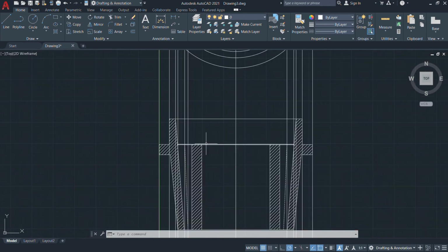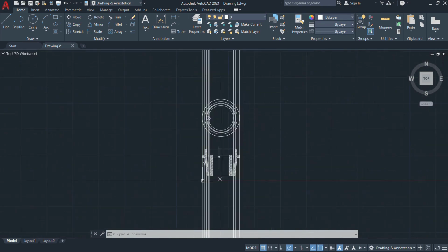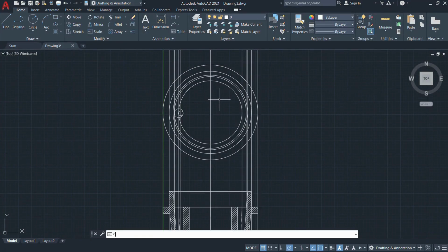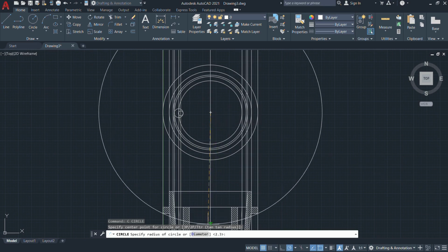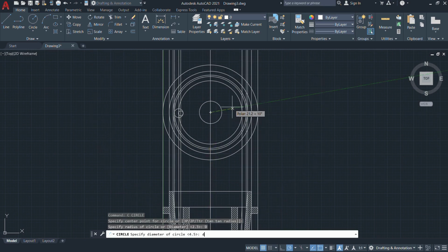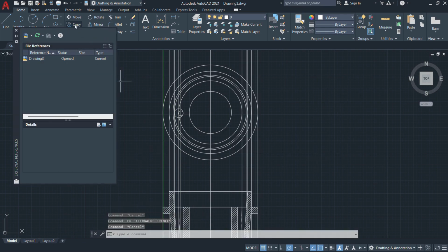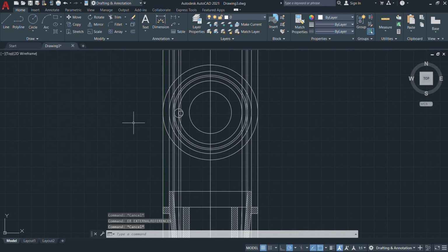Only we need to create the center portion itself. It is nothing but the diameter of 40 mm. So use a circle to draw this particular portion on the center zone. Again, pick a circle from the center point. Initiate a diameter of 40 mm. Select it and mention that. Then we need to remove the excess portions, that is, delete all the construction lines now. Either we can use the E command to erase the portions or we can simply select the overall profiles and delete it.